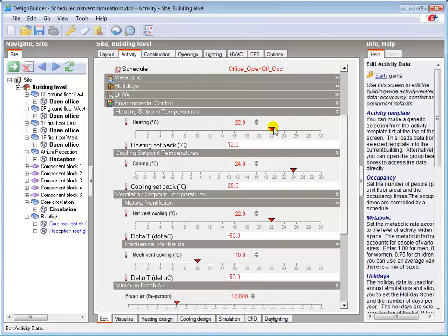This should provide a sufficient deadband to prevent simultaneous heating and venting, i.e. heating using the radiators, which raises the zone temperature above the natvent cooling set point, resulting in simultaneous operation of the heating system and natural ventilation openings to affect cooling. Increasing the number of time steps per hour in the simulation can help to reduce the likelihood of this affecting the results in the model.